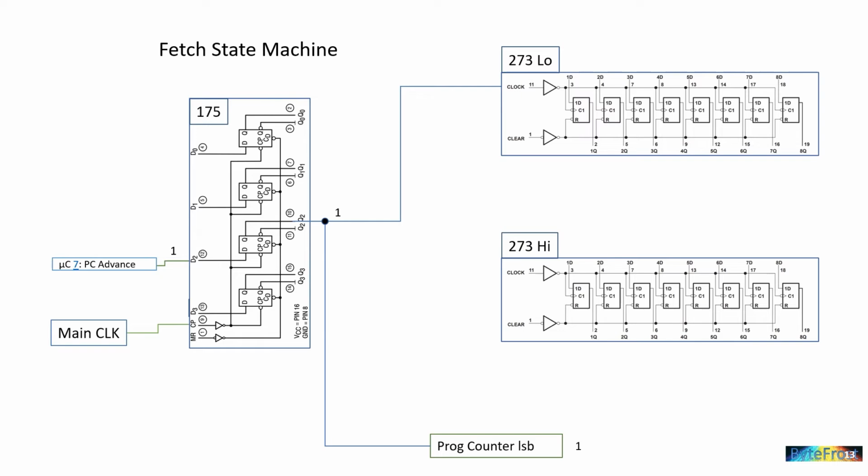In any case, we've now stored the low byte of instruction 3 in the low instruction register, and we can see that the 1 value that we used as a load enable for the low instruction register is also being sent to the least significant bit of the program EEPROM's address input. As the program counter hasn't changed yet, the current input address to the program EEPROM is 7, as we saw before.